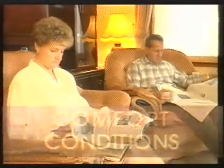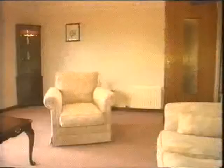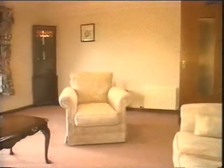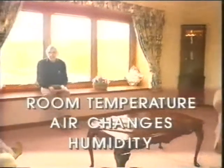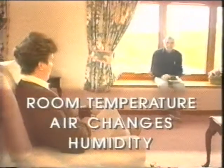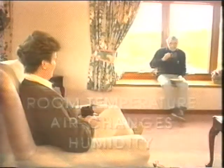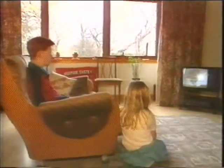When you're asked to design a central heating installation, what the customer's looking for is comfort. So the first thing to decide is what we mean by comfort conditions. There are three factors which affect thermal comfort: room temperature, how often the air in a room is changed, and the humidity. The factors will alter according to which room you're dealing with. They'll also be affected by the level of activity in the room and how much clothing people wear there.